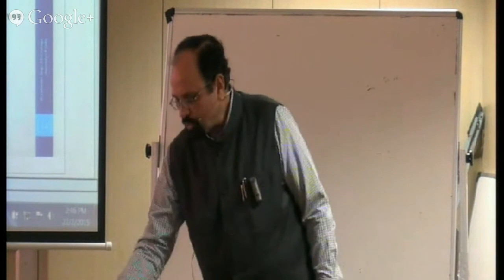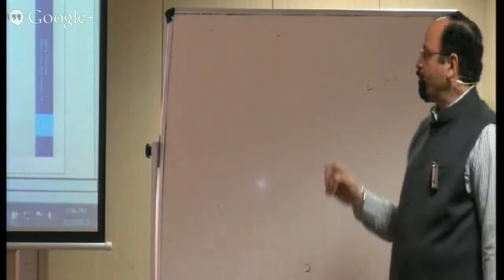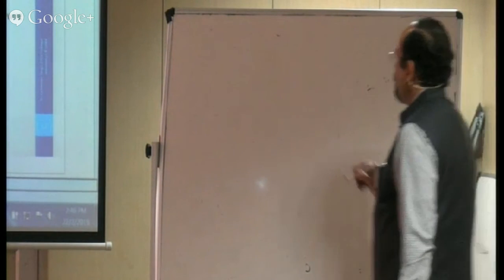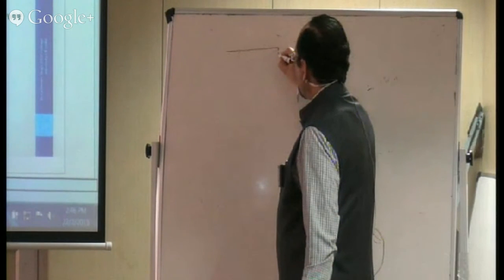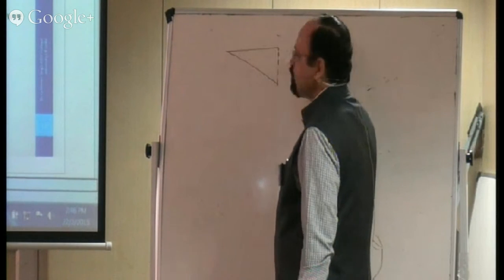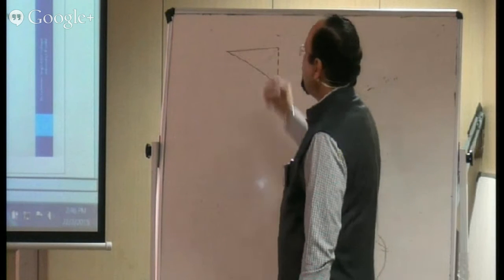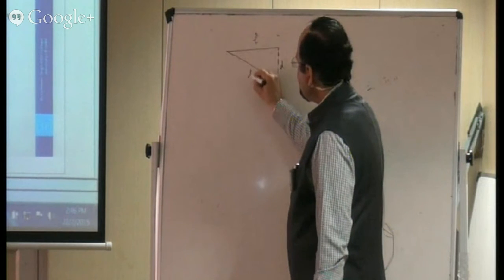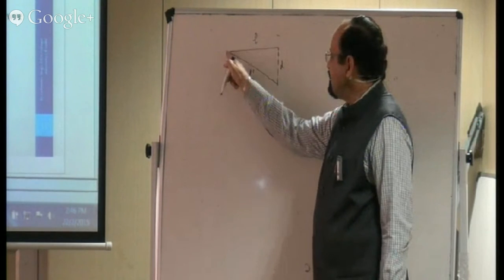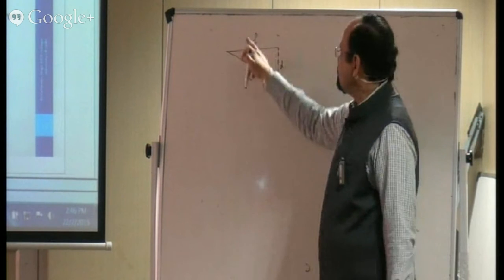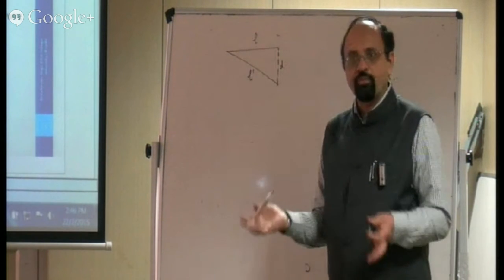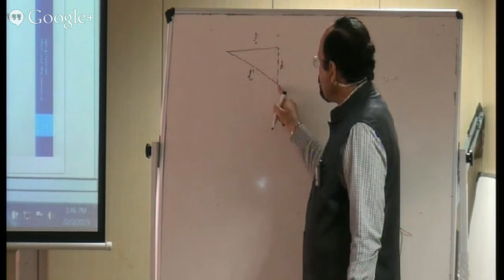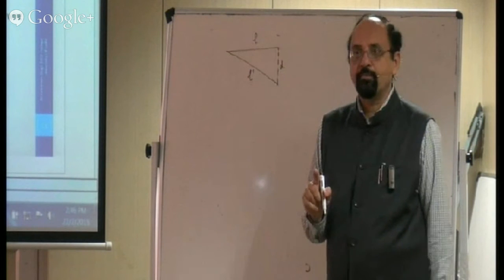But with this question, I want to teach you how to do the approximation when things are given. That is important. Let's take this part of the wire only, because the tension is going to be the same, symmetry is there. Its length is L, pulled like this, and if I say the length is L dash, can I say there is an increase in the length? Obviously, there's a side and there's a hypotenuse. Hypotenuse is always more for a triangular shape like this.